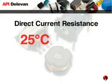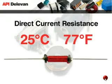DC resistance is normally rated at 25 degrees C or 77 degrees F. Because magnet wires are copper, their resistance goes up as the copper heats up. A baseline is established at 25 degrees C. In custom engineered products, 20 degrees C is often used. In those cases, designers convert based on the coefficient of copper to what the reading should be at 25 degrees C.